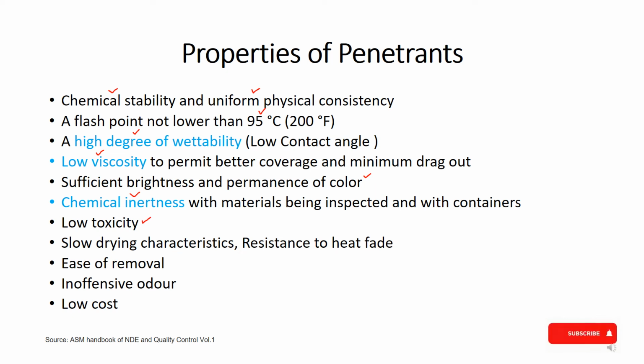It should have low toxicity, meaning it should not impose any threat to the personnel who will be dealing with this inspection technique. It should have slow drying characteristics, because if it dries out at a faster rate, then we will not be able to inspect the workpiece. And there should be resistance to heat fade.